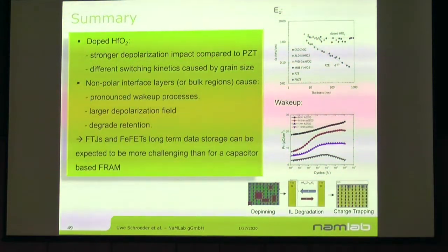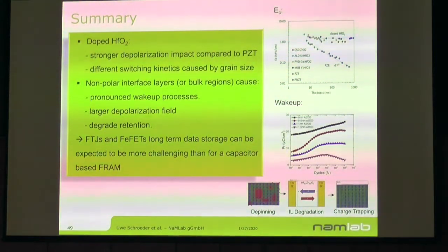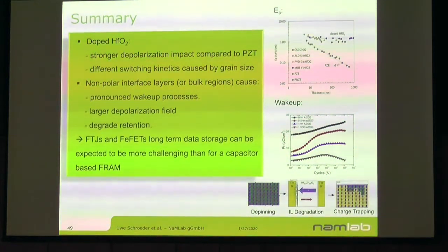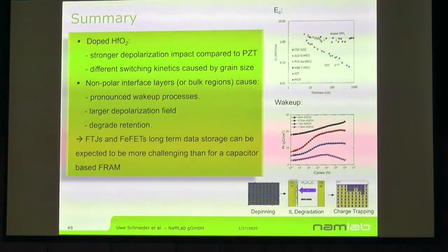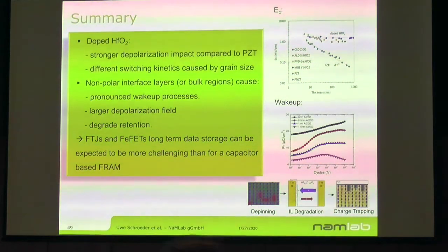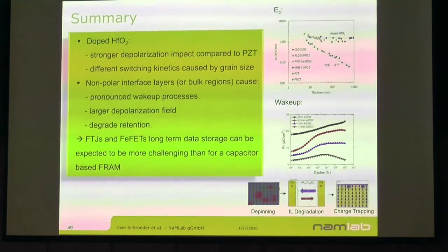Well, that's why we were looking into where this high coercive field is coming from. If we could increase the dielectric constant of the hafnium oxide, maybe by certain doping, then we can also reduce the coercive field, and this is our current hope, that we can reduce the coercive field overall.